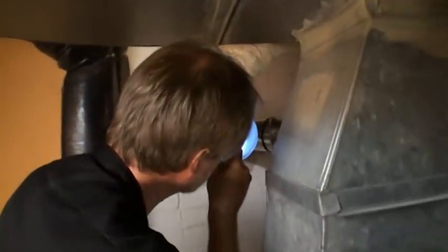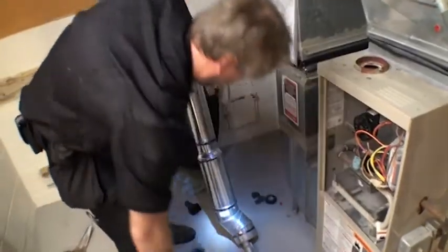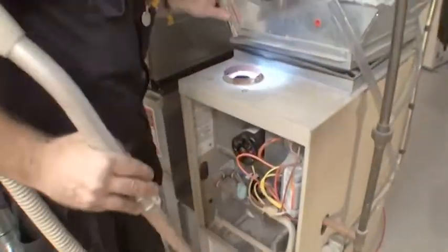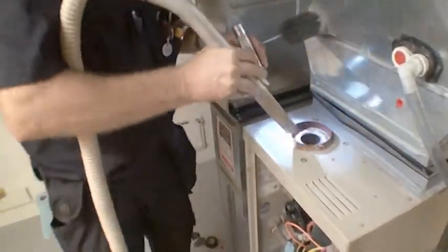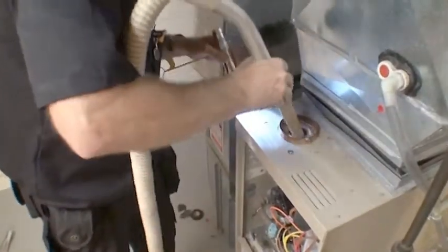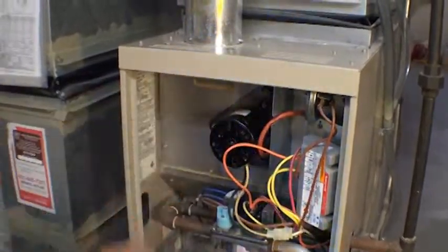If the furnace flue appears to be okay, we expect it to be brushed and vacuumed. Call Community Action if a repair or replacement is needed. Check the integrity of the inducer motor and blower fan blades. If repair or replacement is needed, call Community Action. If not, then proceed to brush and vacuum the fan blades. It is important to oil the inducer motor and ensure the fan blades move freely.